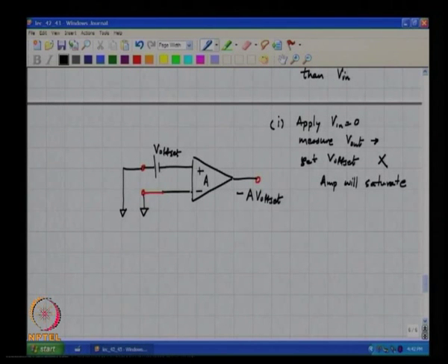Right. I mean, think about this as, I have an op amp with an input referred offset, and I want to find what that offset is. What will you do? So, from your basic op amp classes, you take the op amp and you put it in unity feedback, and what will be the output? This output will be, please check carefully, minus V offset, correct?